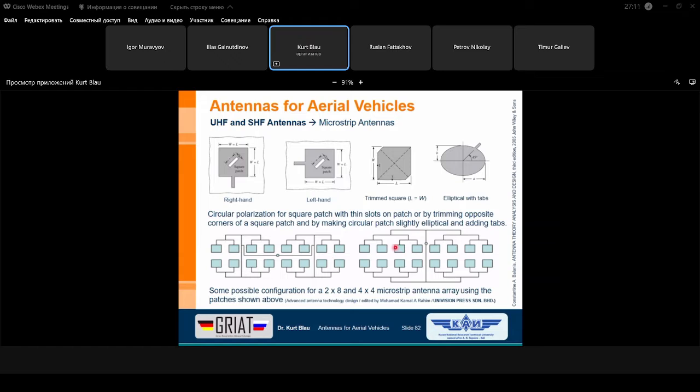And then I showed how we can feed. This is the feed network, or the feed lines. All these strips here are in principle microstrip lines. And we have to consider some special conditions, because if you connect 2 antennas here, then it's clear that at this point here, or at this point, it's the same problem. We have only half of the input impedance. If this is 50 ohm and this is 50 ohm, and we connect this with a 50 ohm line, then we have here only 25 ohms, it's clear.